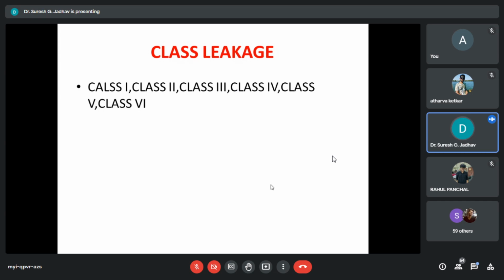Now next is class 2. In class 2, 0.5% of rated valve capacity. And for class 3, here 0.1 of the rated valve capacity. Earlier class 2 is 0.5 rated valve capacity and class 3 is 0.1 rated capacity. And class 4 is 0.01 of rated capacity. See the difference? They are based on their rated capacity.